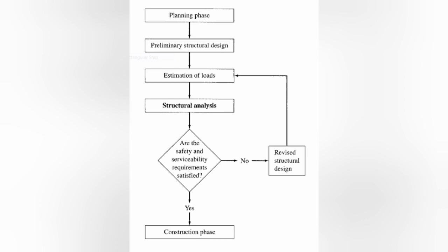You will start with the estimation of the weight of the structures, the dead loads, and then you must determine also the loads that will act on the structure, either the dead loads of those structures on top of it, or the loads of the occupants, the live loads.